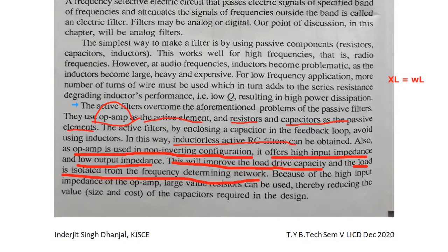And that's why we normally prefer filters with op-amps working in the non-inverting configuration, because it offers very high input impedance and low output impedance, which will definitely improve the load driving capacity, and also the load will be isolated from the frequency determining network.